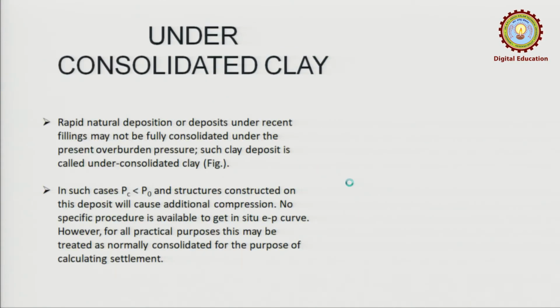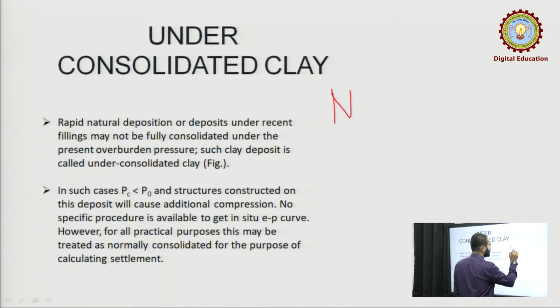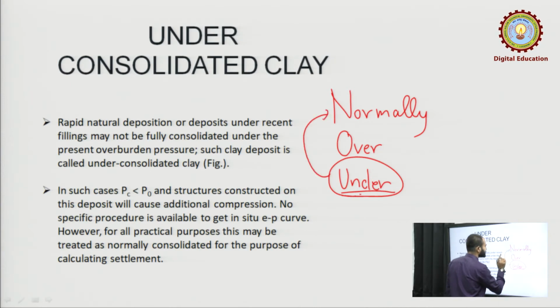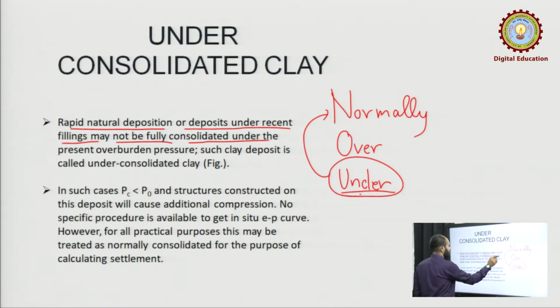Underconsolidated clay. What is underconsolidated clay? We have read about normally consolidated. We have read about the overconsolidated. Now underconsolidated. Actually, this underconsolidated is not of much use because it is taken into this only. Rapid natural deposition or deposits under recent fillings may not be fully consolidated under the present overburden pressure. Such a clay deposit is called underconsolidated.